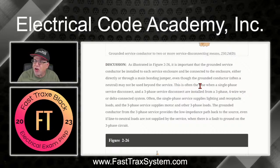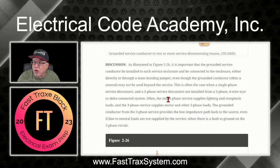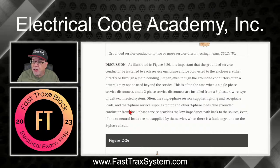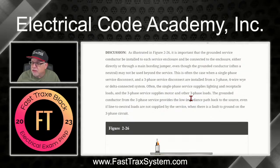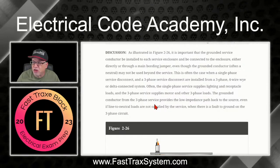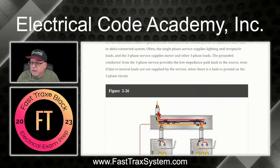It says, this is often the case when a single-phase service disconnect and a three-phase service disconnect are installed or derived from a three-phase four-wire Y or delta connected system. Often the single-phase service supplies the lighting and appliance loads, okay? And the three-phase applies to things like the motors or other three-phase loads. The grounded conductor from the three-phase service provides the low impedance path back to the source, even if line to neutral loads are not supplied within that panel by the service, okay? So this is a good example.